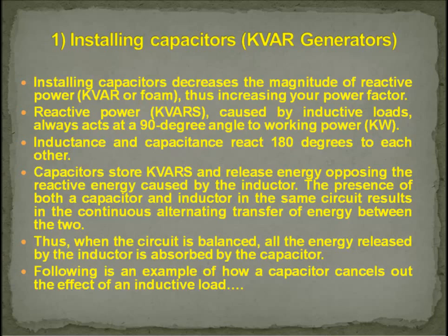Installing capacitors decreases the magnitude of reactive power, kVAR, thus increasing your power factor. Reactive power, kVARs, caused by inductive loads, always acts at a 90-degree angle to working power, kW. Inductance and capacitance react 180 degrees to each other.